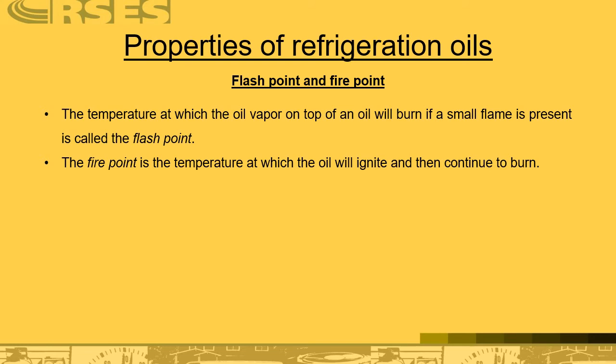Flash point and fire point. The temperature at which the oil vapor at the top of the oil will burn if a small flame is presented is called the flash point. The fire point is the temperature at which the oil will ignite and continue to burn.